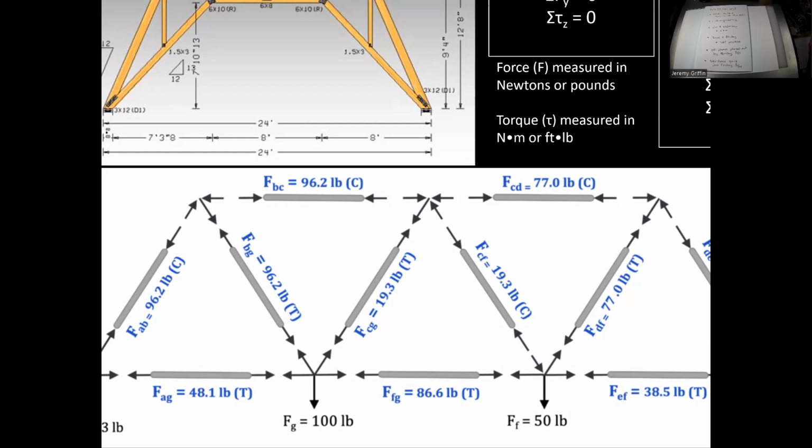Great, you're building it out of steel. Well, you still have to know exactly how much tension, because if you know what this force has to be, you'd want to scale it up to have some cross-sectional area. You probably want to use a big, thick steel rod right here compared to this one, because there's more force going on here, more tension force, right? But again, this is an optimization question. There's also an economic side to this whole thing.